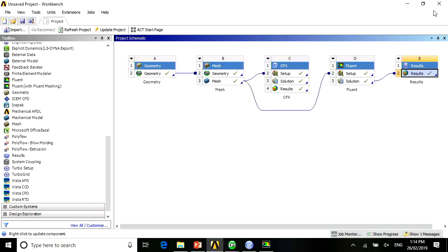Fluent does better with particle flow, like solid particles in a flow, because they went in different directions in developing the approach. So, for example, for tracking of particles, I like Fluent more. For solving gas-liquid flows, CFX went with its own approach, because I know the developers.